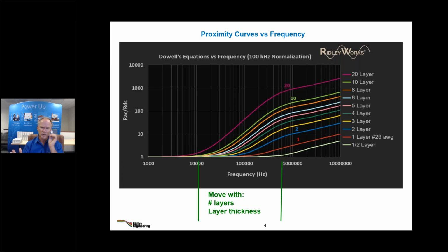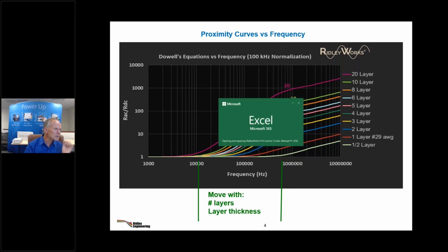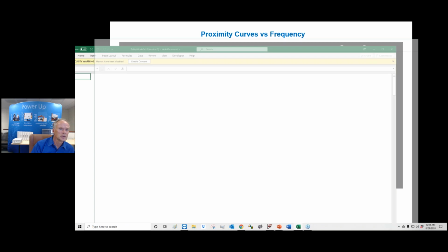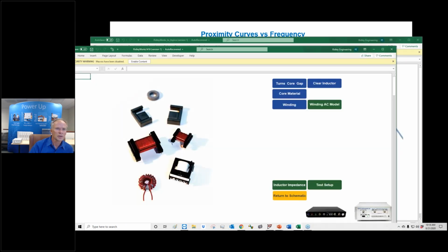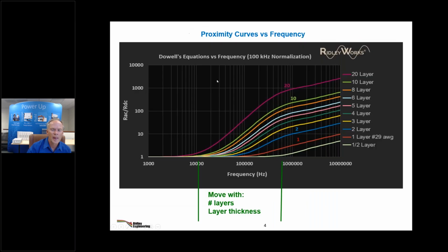Good question from later on there, right? Okay, we have a question. If the core current had DC and AC components like in a forward converter, is the AC resistance affecting losses only for the AC component or for the entire current?